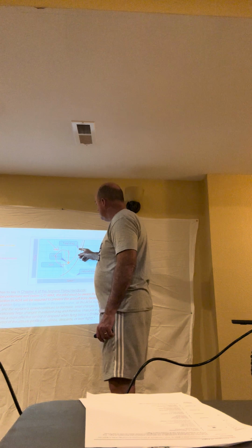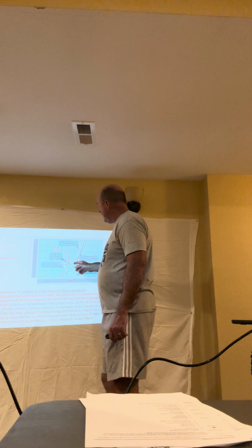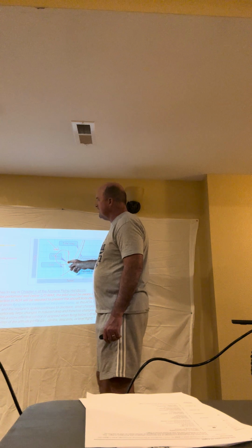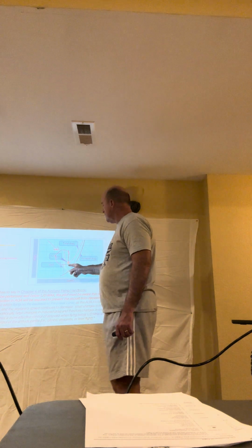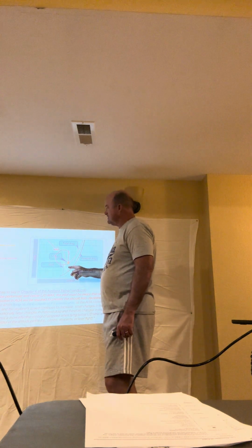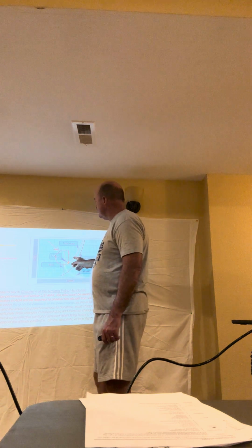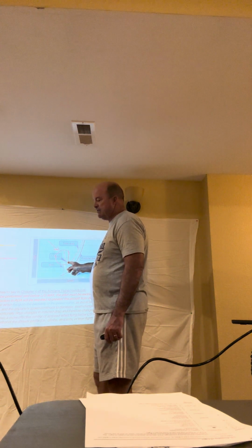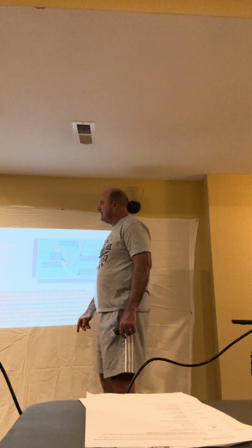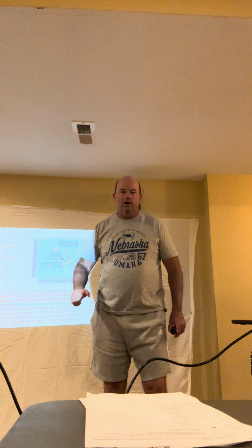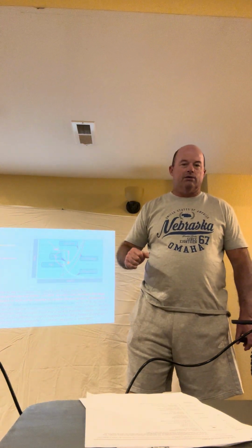But as you slow down, the drag decreases, and they say you get on the reverse command. So as airspeed decreases below the lift drag ratio, total drag increases. So as you decrease it, then the drag has more of an impact, and you kind of get what they call a reverse command. So this is kind of fun when we're flying an airplane. If you get real slow, you just have to fly the airplane differently, right? So all this stuff is designed to teach you how to fly the airplane and why you're flying it that way.